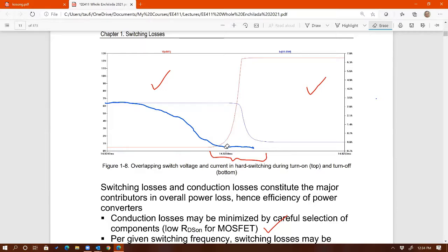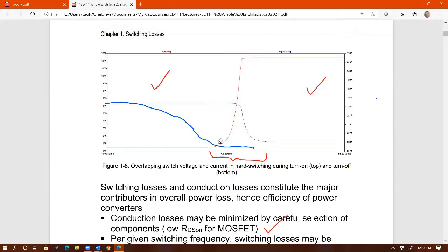If you can still turn on the MOSFET, but reshape the waveform such that it does not follow a square wave, then you could theoretically minimize the overlapping amount. So again, we have control over when to turn the switch on and off, but the shape of the waveforms, either voltage or current or both, could be determined by external components of the circuit. Hopefully that makes sense without going through the details of soft switching yet.